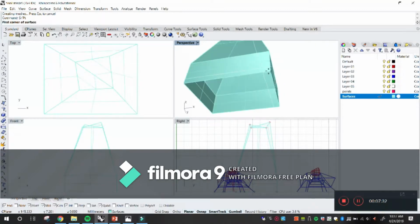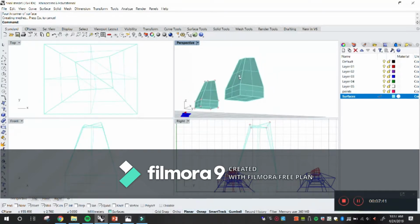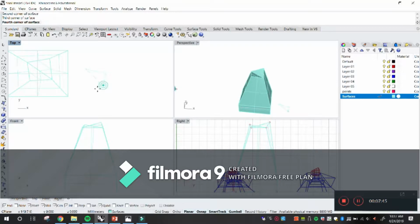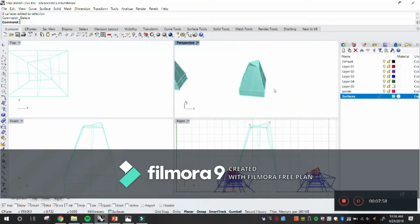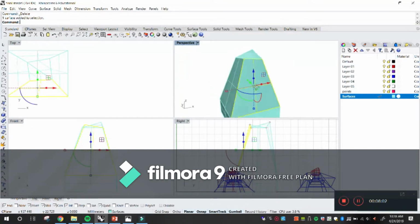I'm gonna come right here to the bottom and snap and cap it as well from the bottom for right now. Okay. So remember, if it's 4 points, it will close automatically, right? So 1, 2, 3, and at the 4th one, it's gonna close. If you're only doing 3, 1, 2, 3, on the 3rd one you need to do a right click or an enter to tell it it's a 3-pointed surface. Okay. So we delete those. Now Fernanda's question is the right question, right? Okay, so I have all of the surfaces.